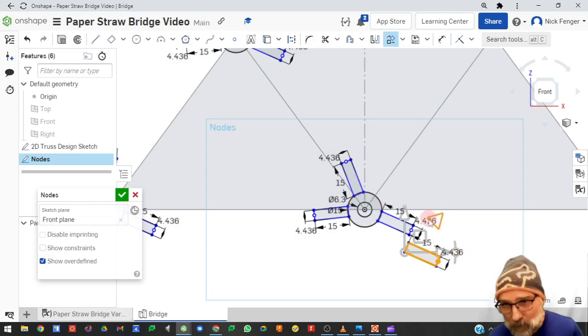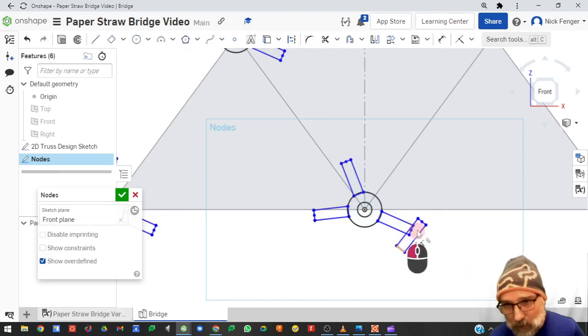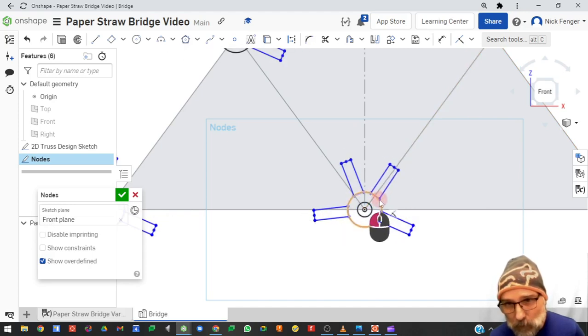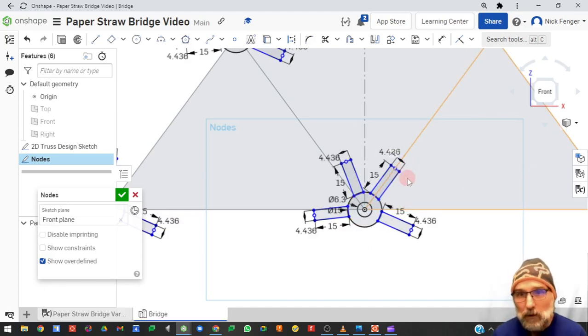We got to put it up here, so you can rotate it a little bit in kind of the right location. Note it's not going to create any constraints right now, so we just click, and now we can get it up there easier. Shouldn't be creating any constraints anyway. Okay, we want one constraint there, and there, one coincident.